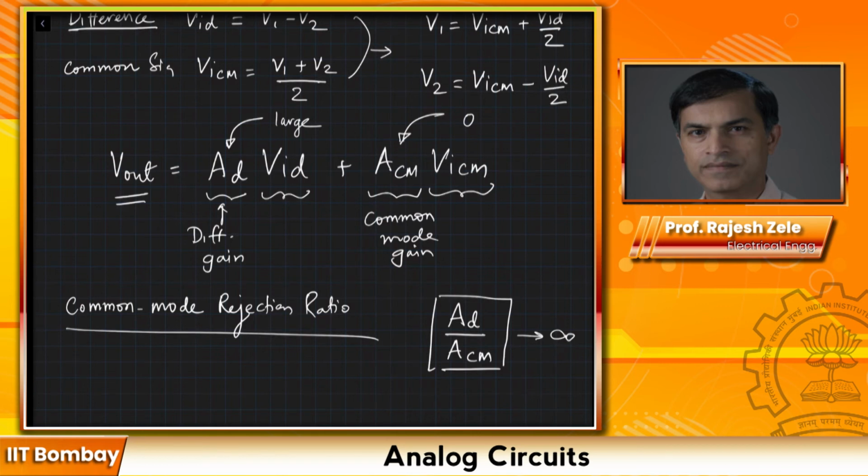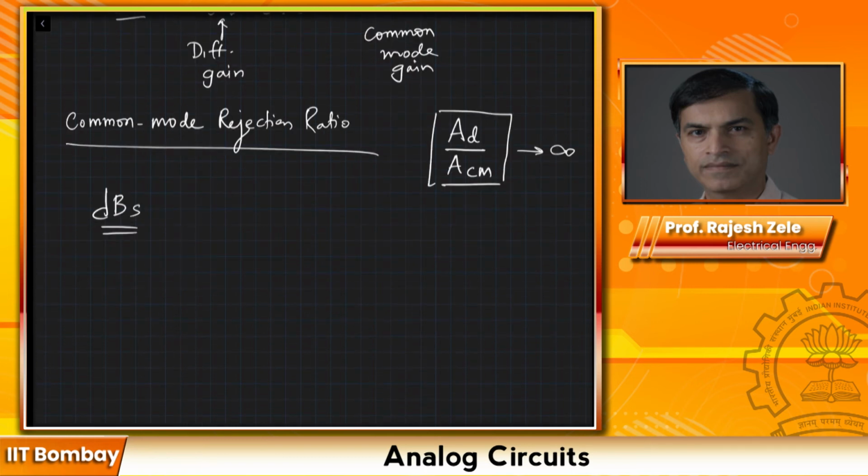Now these numbers can be very high, so let me take one different step to introduce one definition for you, and the definition is decibels. dB is applied to ratios only. Remember that you cannot take dB of 1 volt. You always take dB of a ratio of two voltages. All right. So the dB term is defined as 20 log to the base 10 of a ratio.